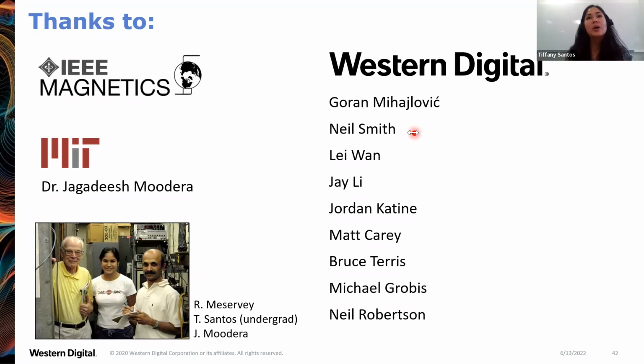Yes. So the hard mask is tantalum nitride, diamond-like carbon, and chrome. And we define it using a reactive ion etching process. The hard mask will be largely consumed by the milling as it's trying to protect the MRAM pillar.